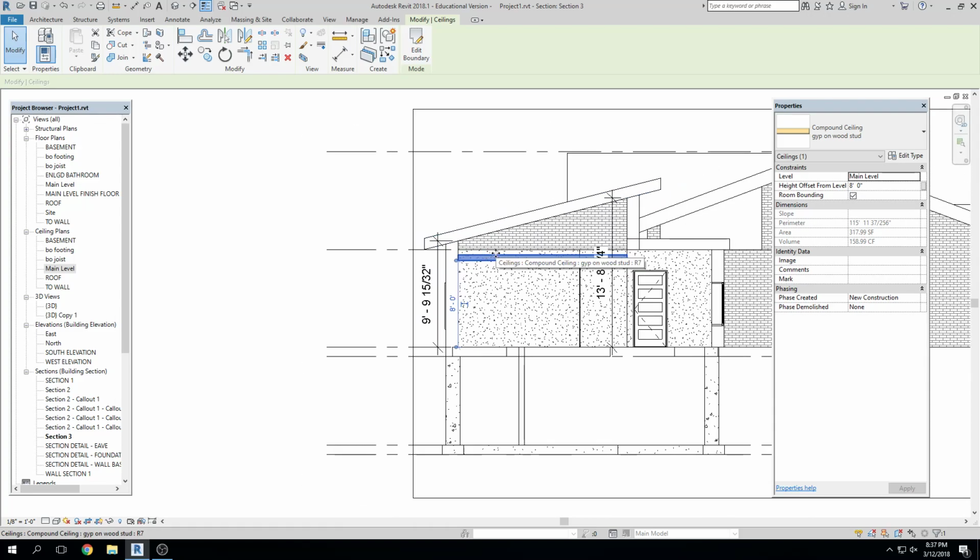When I'm working on drawings, I get it in there as accurate as possible, but there are always times where it's so close, but just not quite. The bad thing about ceilings, I wish they would change, although I understand why, is that I can't align a ceiling to a roof. You look at it and think, I'll just align it and it'll lay right in plane with the roof. But we can't do that.